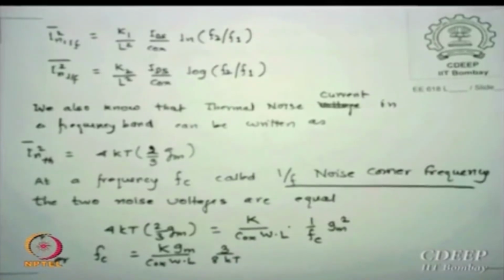So when I define bandwidth for my amplifiers or circuit, please remember it also influences your noise voltages, or at the end we say the signal to noise ratio may deteriorate. This was not known earlier, but now you can see there is a dependency coming from here.